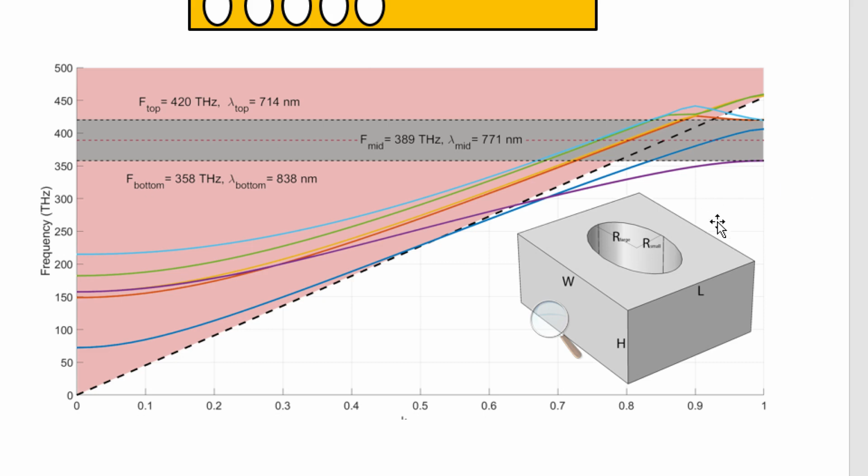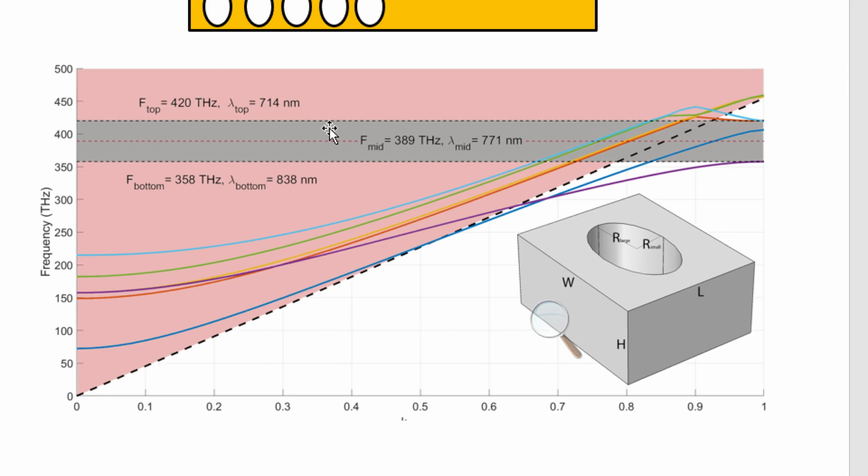By that I mean we can have band gaps, for example, for only TE modes. The blue line is a different polarization, and by definition they should be orthogonal. So if you have a TE polarization, you shouldn't couple. But there is a risk here. If you have any imperfection in your system, like asymmetry or something, you might actually couple due to scattering.